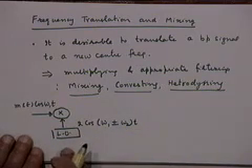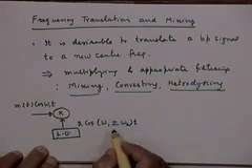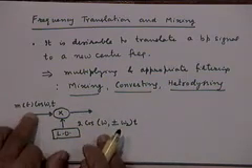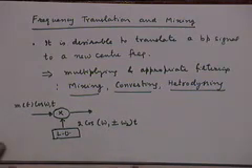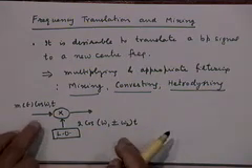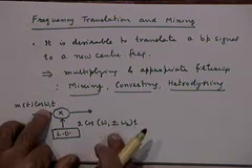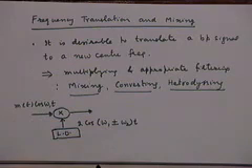So I take a local oscillator with a frequency of either ω1 plus ω2 or ω1 minus ω2, and then when I multiply these two, I'll get a sum frequency component and a difference frequency component, right? The sum frequency component will be centered around 2ω1 plus minus ω2, which let's assume is quite large and can be removed by an appropriate filter.